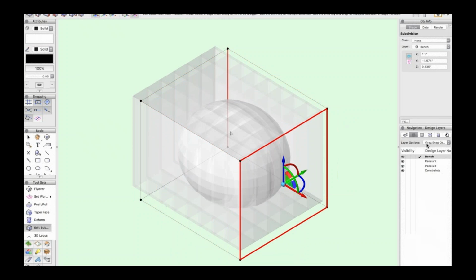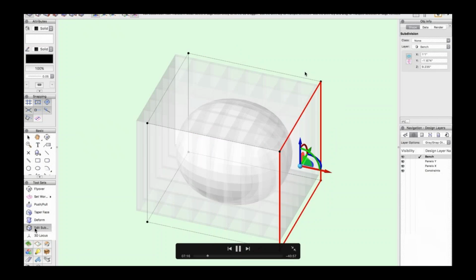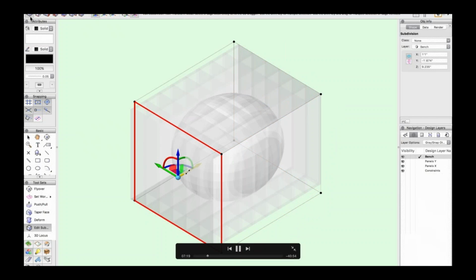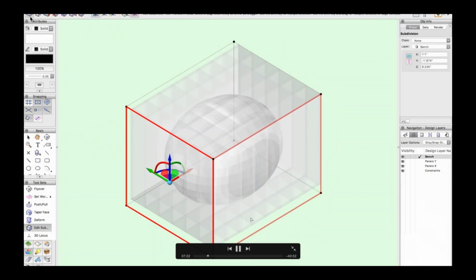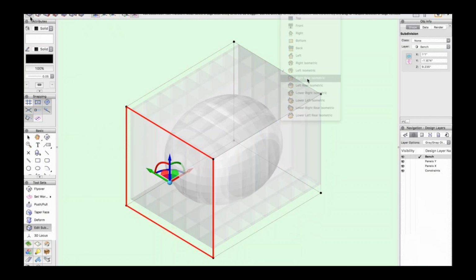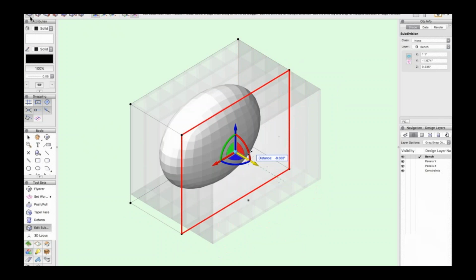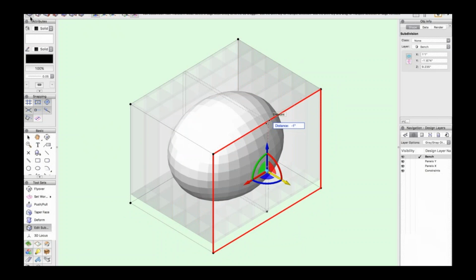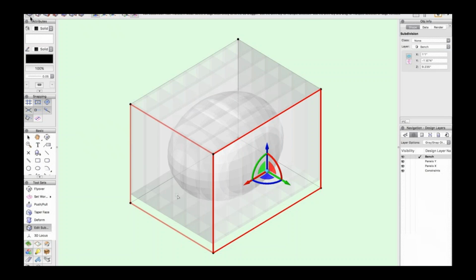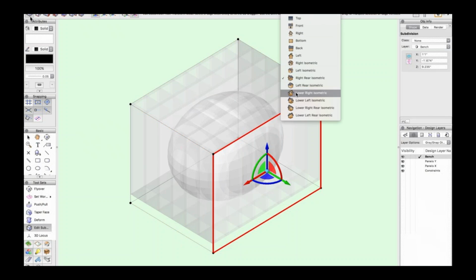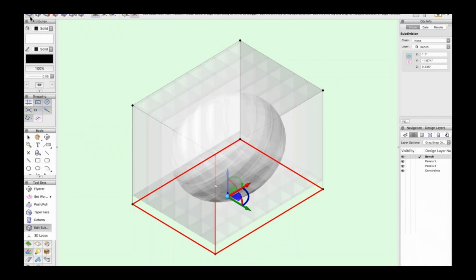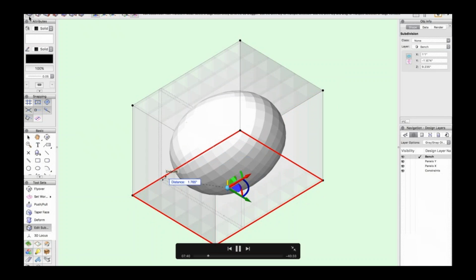Well, I'm using the 3D dragger tool up at the top. When I select the subdivision modeling tool, the first setting there gives me the ability to actually manipulate the faces, edges, and points of the cage. And the cage essentially will affect the primitive inside as you move the cage. And you'll see me moving the faces of the cage there with the 3D dragger. Now the 3D dragger is available when you click on this first mode of the subdivision tool. Then the 3D dragger tool is just here to the right-hand side, just to the right of that pipe there.